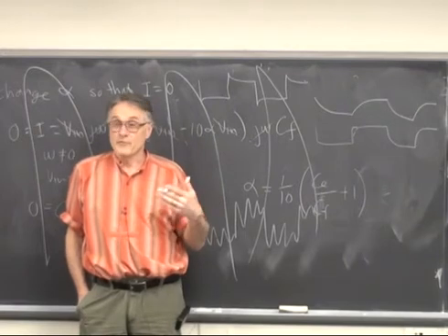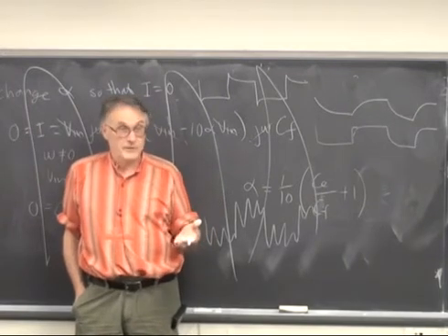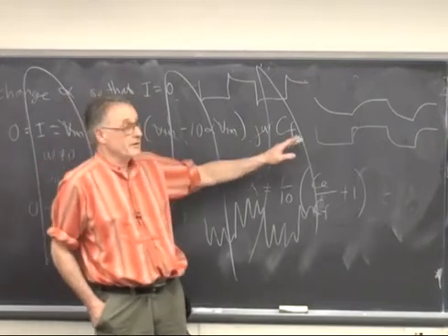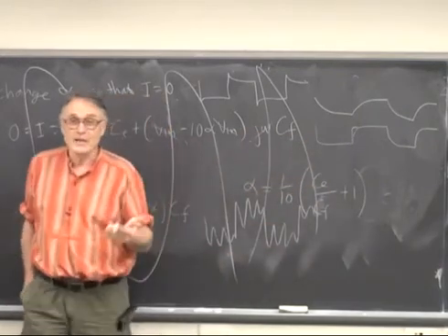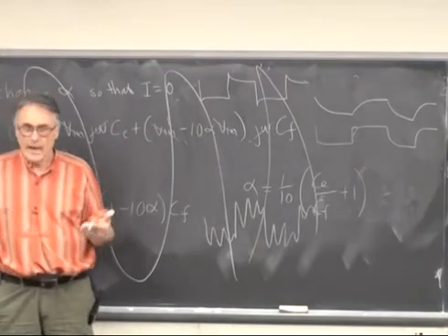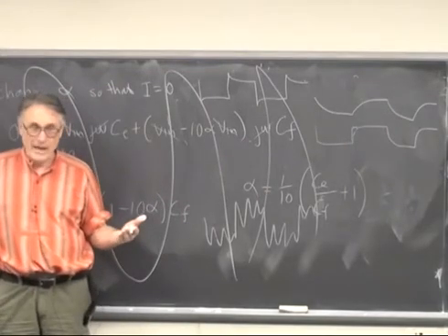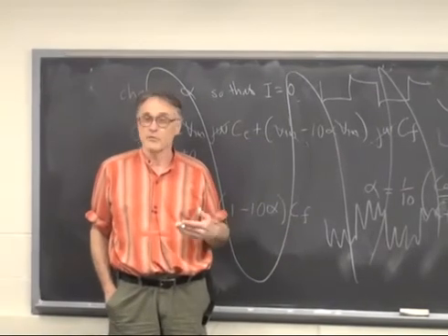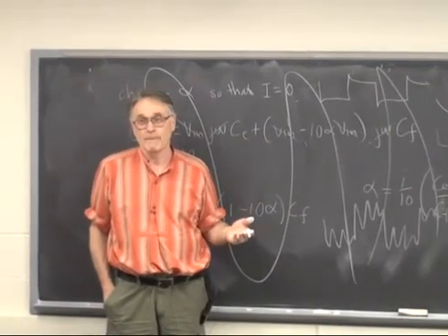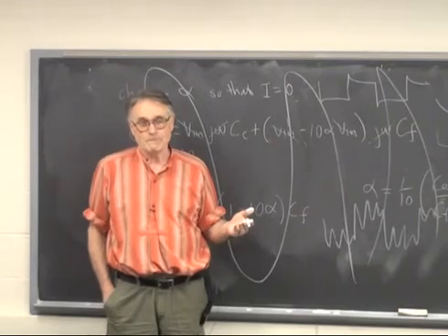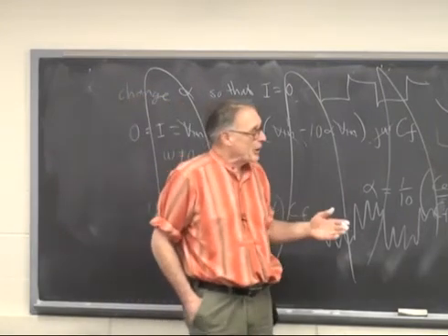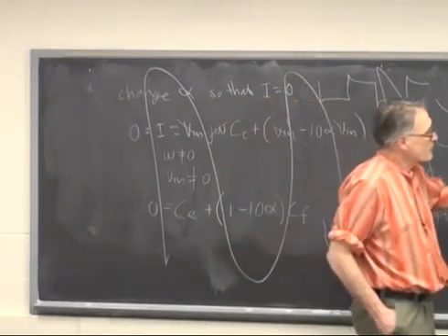So you've turned up the high frequency gain, effectively, because you now have almost infinite bandwidth. That means any noise of any frequency at all will be amplified, including stuff that's way outside the bandwidth of what you're interested in. There's no filter. There's no filtering at all. There's no low passing at all.